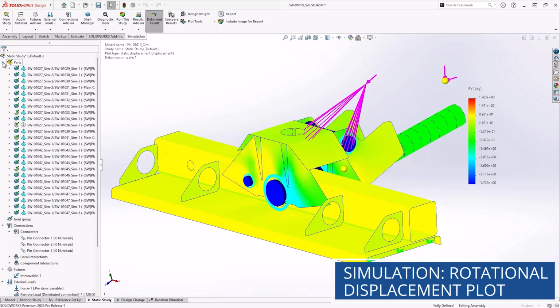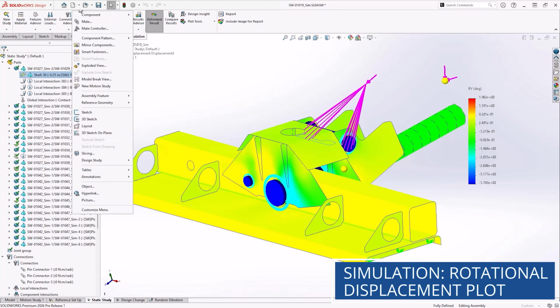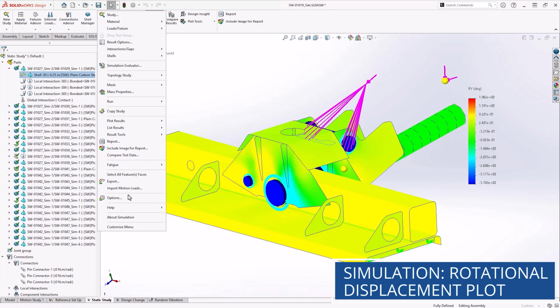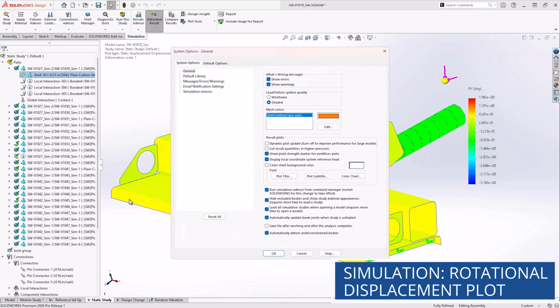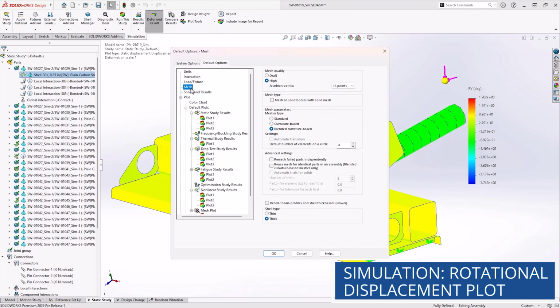This model is set up using primarily shell elements, ideal for analysing thin plates while ensuring fast solve times and retaining accuracy. Typically, a thickness to span ratio is used to decide between thin and thick shells, where thick shells will account for shear stress through the plate's midplane.